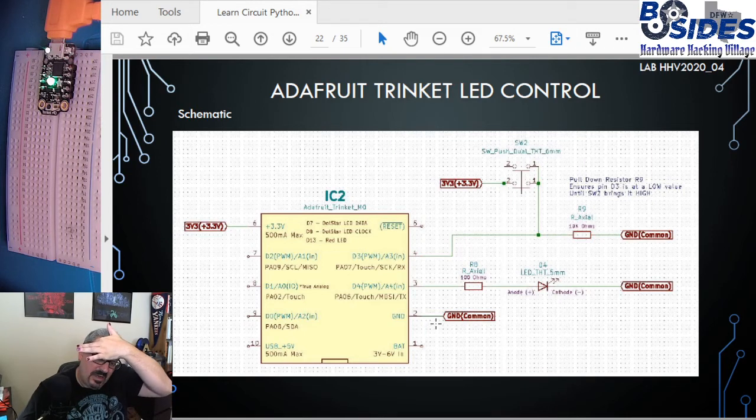and then it's going to ground. Now, unlike my previous schematics that I used in some of the other classes, like the Arduino class, I'm not drawing the lines all the way to reconnect to everything. Instead, I'm using labels, which show that they're all interconnected. I think it makes it easier to read, and when I do schematics for my projects, not for training, I typically use labels, so I wanted to introduce that here. So ground here is going to the ground pin. So that's our LED. Now we also have a button that we're going to read from.